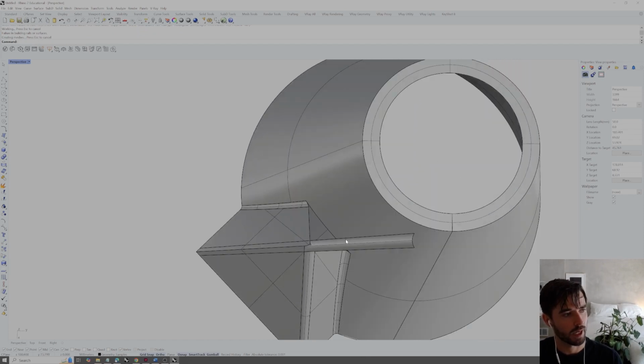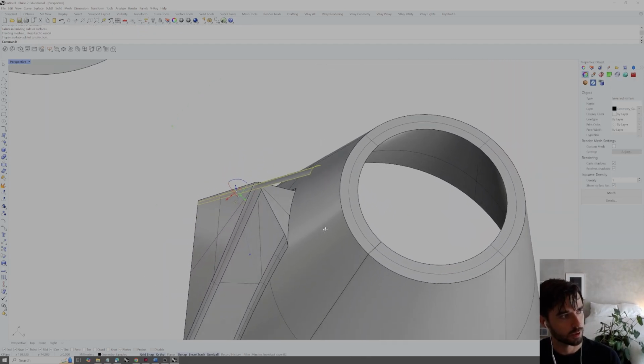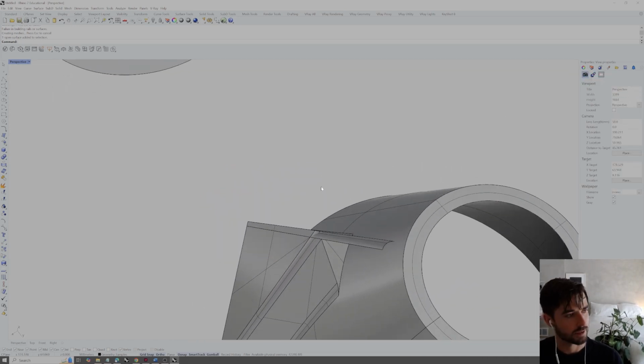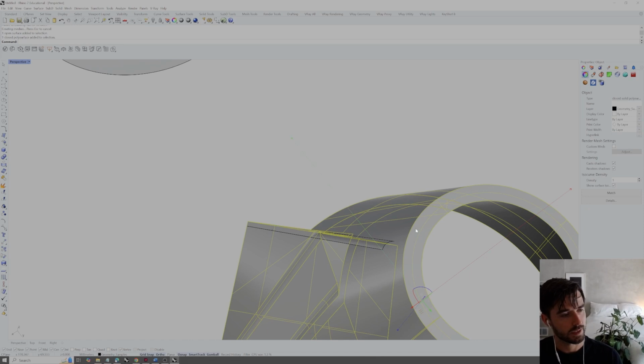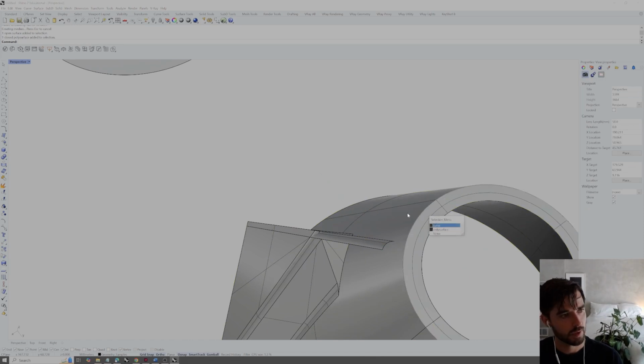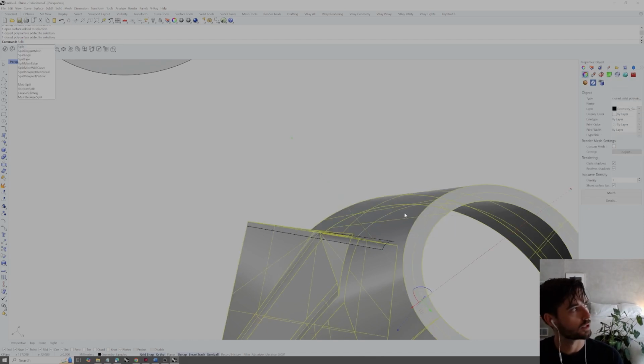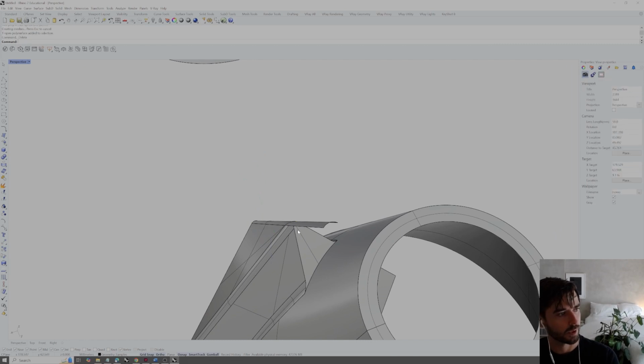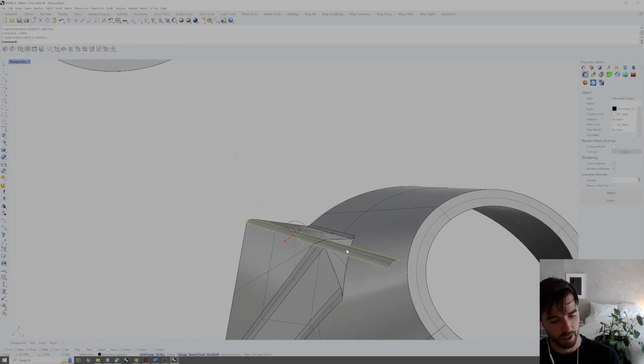Sometimes it will give you an error like this, where it's actually just produced this kind of radius geometry for you to try to manually split. So if that is the case, you'll have to go through and take your base geometry, and using the split operations, type split, select that radius and hit enter. It's now cut off a portion of our geometry, which we can delete. We now need to select that kind of radius piece that we just cut our geometry with, hit enter.